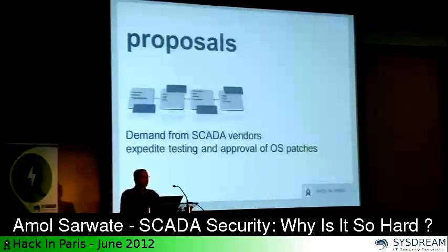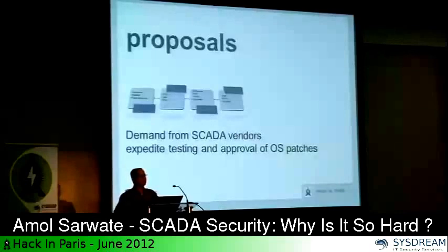And demand from your SCADA vendors that they expeditiously test patches and approve them. In some cases, it's even worse. When Microsoft releases a patch, the SCADA vendor then recompiles the patch, and that is the patch that you can apply on your SCADA system. So there is a lot of time lag, which gives precious time to hackers and attackers to basically compromise systems.